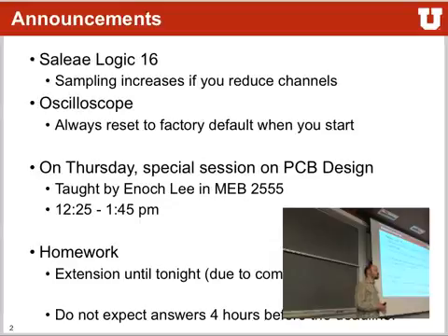Another tip that's always good for oscilloscopes: before you start using them, reset them to factory defaults. You never know what state the oscilloscope is in when it comes up, who used it before, or what settings they put in. If you're completely lost, reset to manufacturing defaults. That way you know the state of the scope. It's usually a pretty decent state, and from there you can dial in whatever you need.